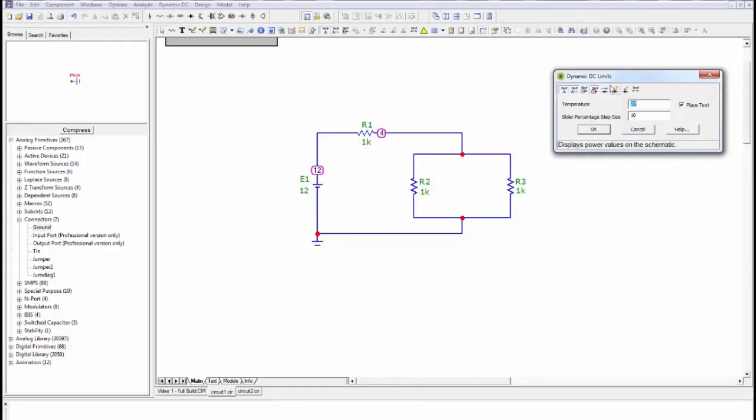And on your little pop-up box you can see that there's a little voltage icon here, so if that's already selected, if I click on that, they go away. So put it back on again, you'll notice the voltages appear. Now of course there are 12 volts across the battery to ground, and it indicates that there with this 12 volts. And it's saying we have 4 volts on the right side of R1, 4 volts between that point and earth. Okay, so all the voltages reference earth, which is node 0 as you remember. Let me take the voltages off.